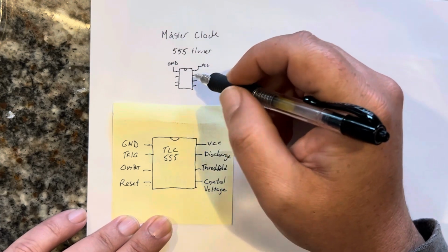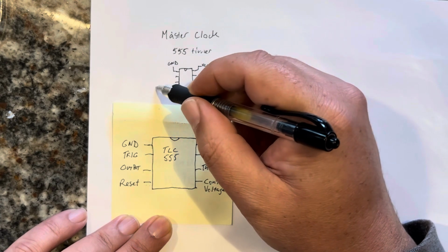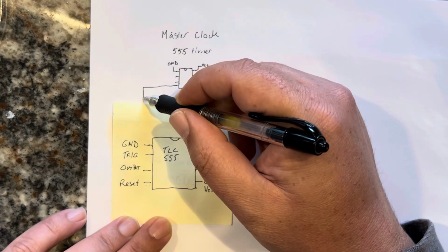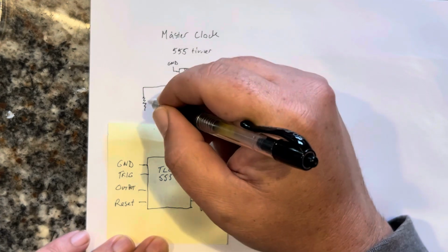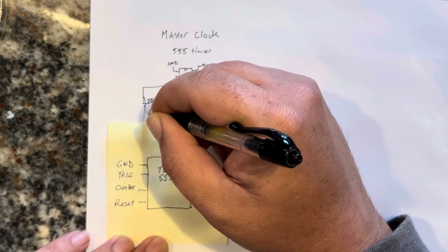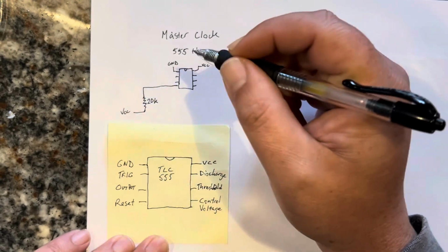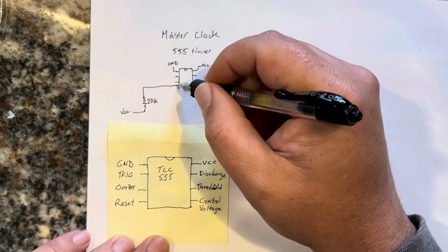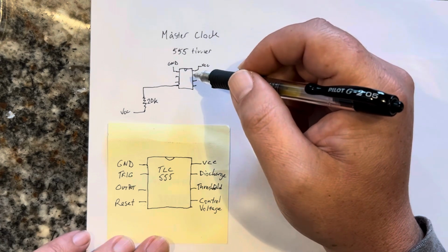What I did here was the reset pin I pulled high through a 20K resistor, and that will prevent the clock from just resetting spontaneously.